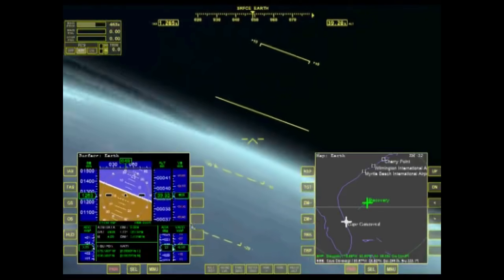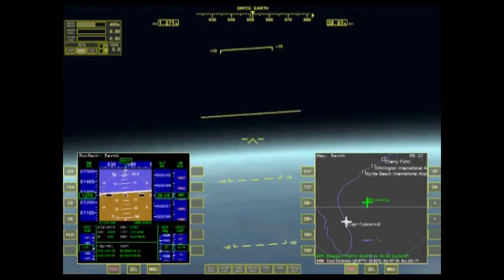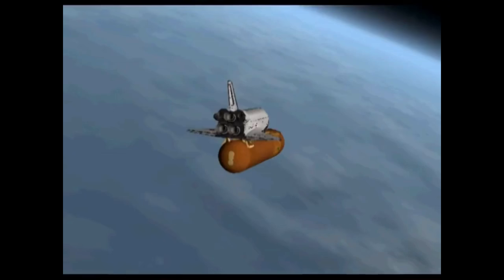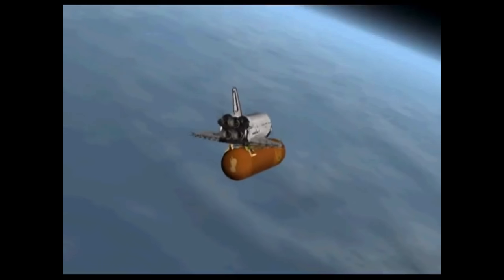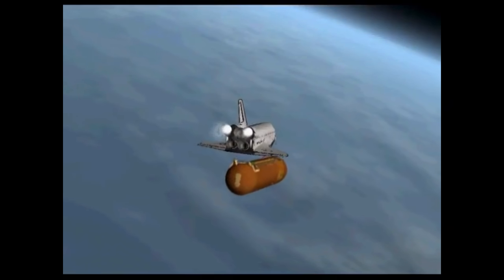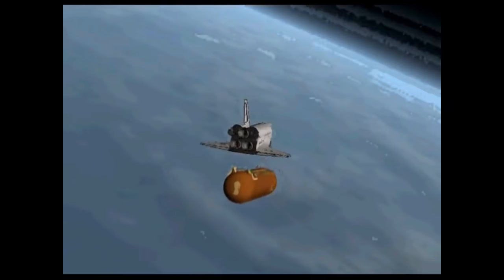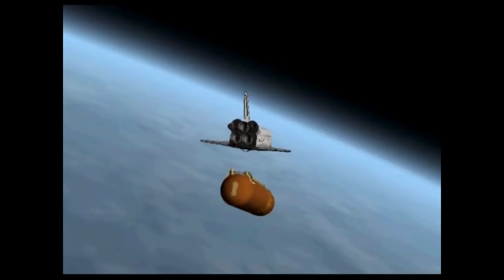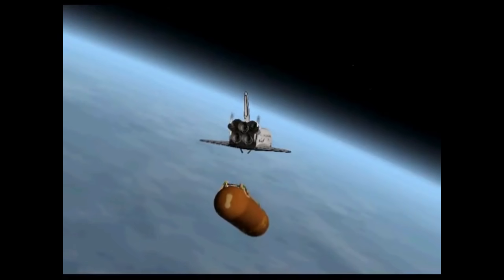When this happens, the shuttle can't maintain its weight and will begin to drop like a stone. Because of this, the external tank would be dropped, and the shuttle will not be able to reach a runway. The crew would be forced to bail out of the orbiter before it crashed into the ocean. However, thankfully, as stated, the RTLS abort option, referred to by some as a, quote, unnatural act of physics, never needed to be attempted on a real flight.